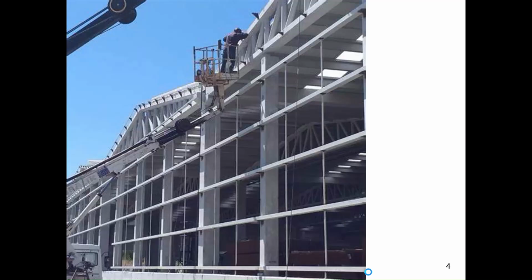More common in buildings, again, I showed this example the other day. We've got some columns that are perhaps carrying the vertical load from the roof, and we also have this glazing support system. These horizontal members are called girts. They're going to take the pressure from the cladding, distribute those loads along those members, and then transfer that force into the columns. And so in addition to the vertical compression force the column has to carry, it's also going to be carrying some transverse or lateral loads, which would result in some bending in that section.